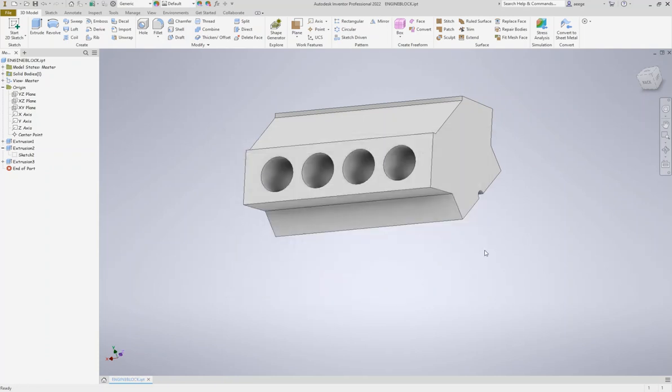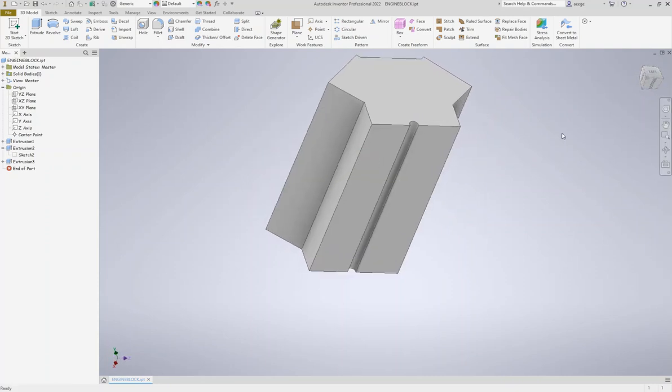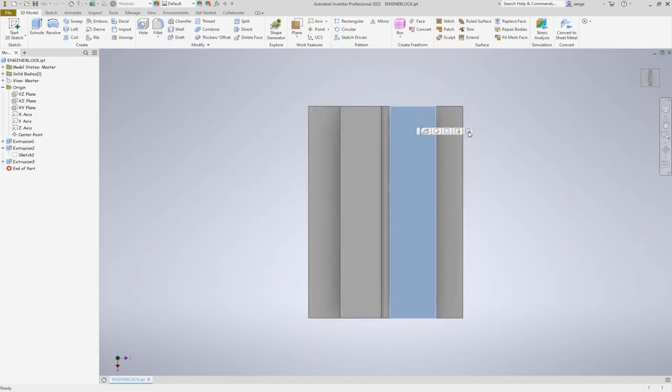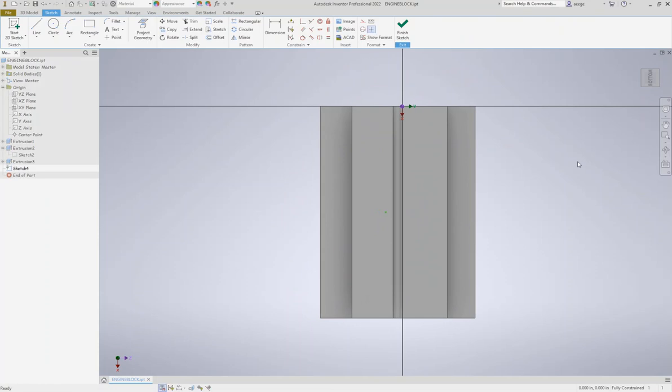What's more, there's a little bit more work to do. This time we're going to turn it around and look underneath, and then create a plane here. We need to empty inside this. So to empty inside, we need a rectangle, draw a rectangle, and then offset this rectangle.